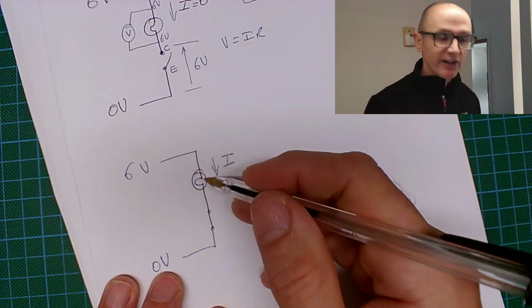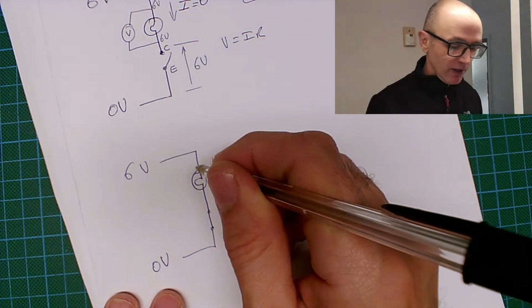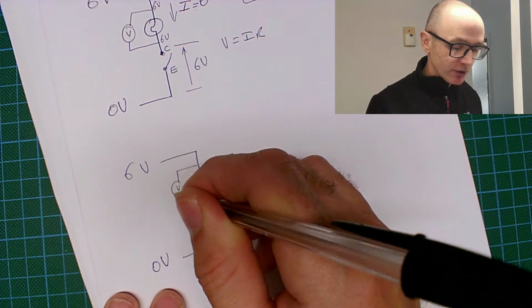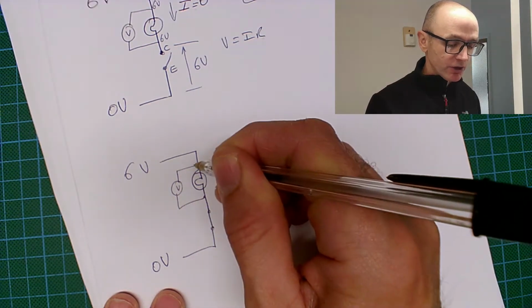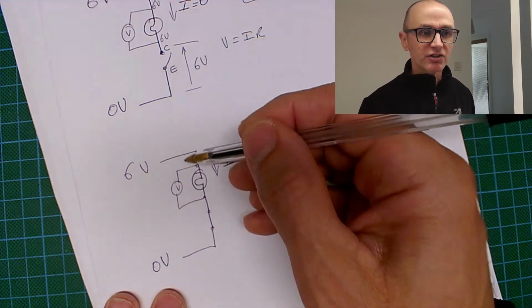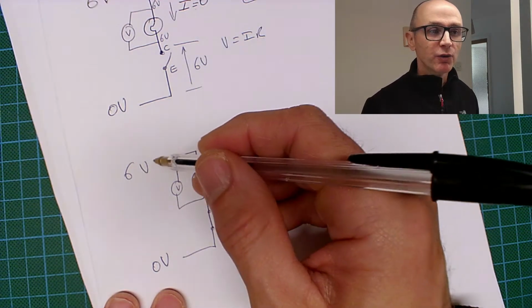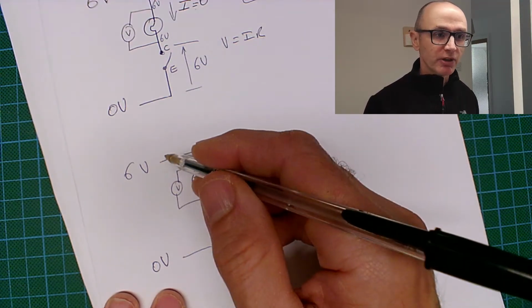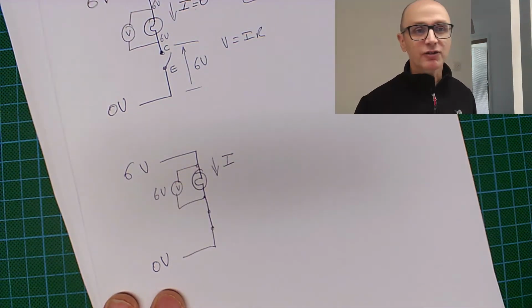And because we've got current and we've got a resistance in the filament of the lamp, then if we were to measure the voltage drop, we will also have a voltage drop. And in this particular case, we're going to have the full supply voltage. There's no other resistance anywhere else. So we'll have this full supply voltage drop across that, which will be 6 volts.